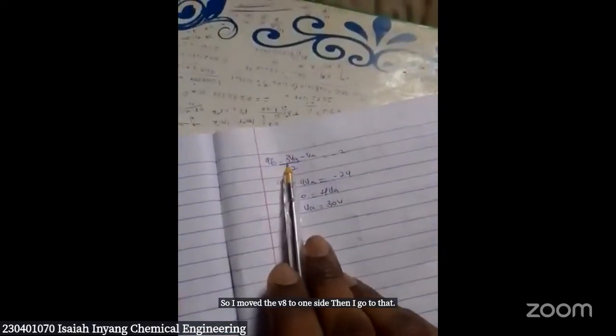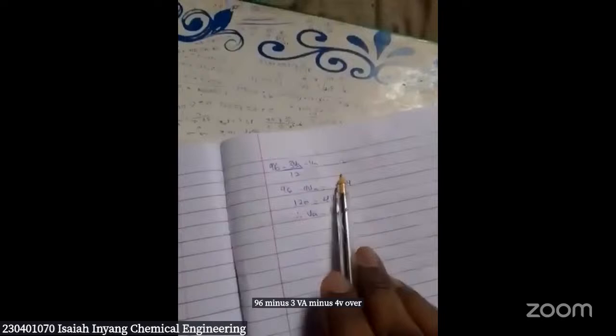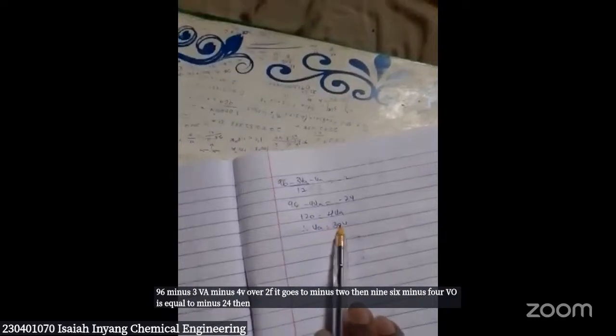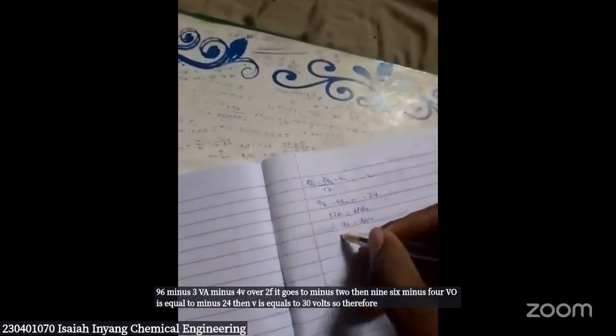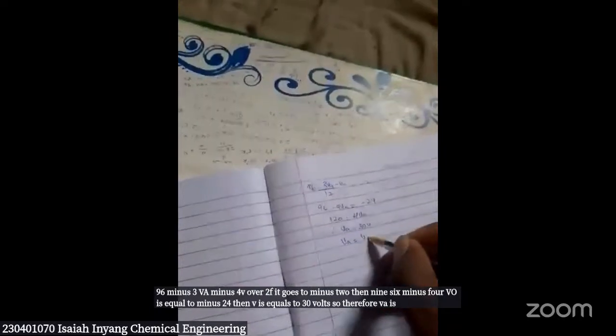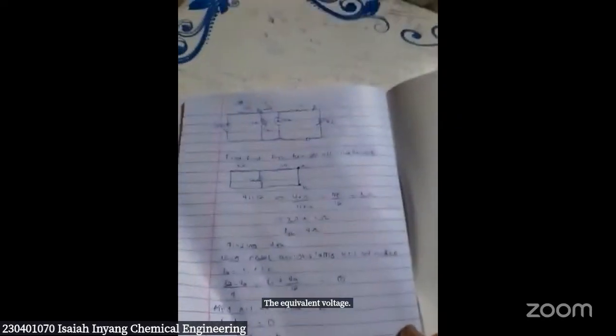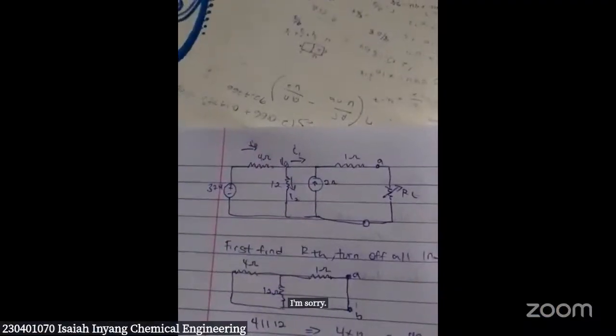So I moved the VA to one side. Then I got that 96 minus 3VA minus 4VA over 12 is equal to minus 2. Then 96 minus 4VA is equal to minus 24. Then VA is equal to 30 volts. So therefore VA is the same thing as VTH. That's our equivalent voltage. Where is your diagram? You have not done the equivalent circuit diagram. The Thevenin equivalent circuit diagram. You need to draw it.